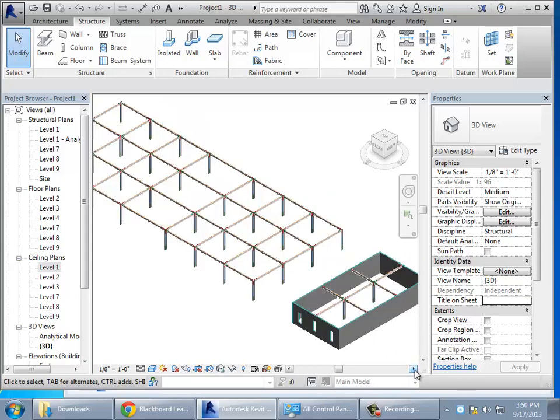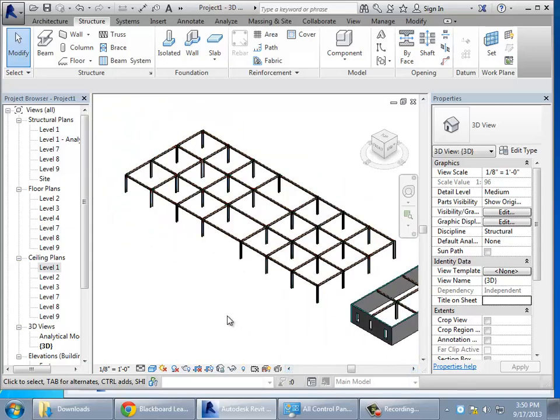Actually, before I go much further, I should be a little bit better in terms of how this is going to be modeled, just to give you a little bit of nuance that's good in terms of construction. When you measure to level 2, level 2 tends to be the top of the floor. And what happens is the steel beams don't actually run up to the top of the concrete. They recess them. What they want to do is ride underneath. There's usually some concrete, a little bit of steel decking, some distance between the top of the subfloor and the top of the steel beams. They're actually recessed, and it'll vary depending on the specifics of your system, how big the concrete decking is, and so on.